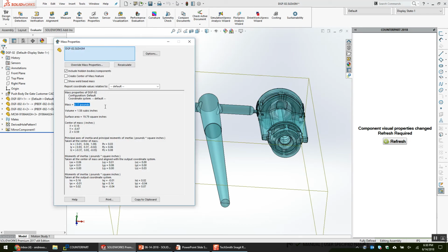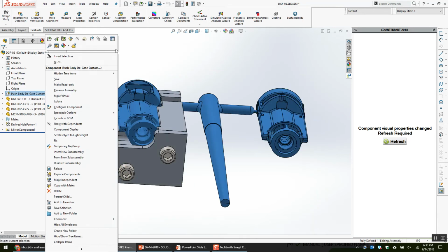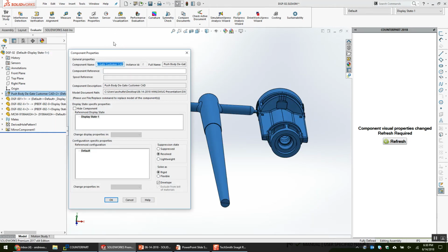So the envelope option does two things. Great question, slightly off topic. No problem, we'll cover it. We got the time, right? We got 10 minutes. So what the envelope option does, and I don't know why they call it envelope, and there's not a whole lot of really great documentation for it, but it basically means here's an item that I don't need, that I don't want, that doesn't exist in the assembly, but I need from a geometric design use standpoint.